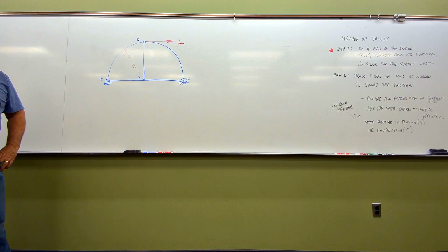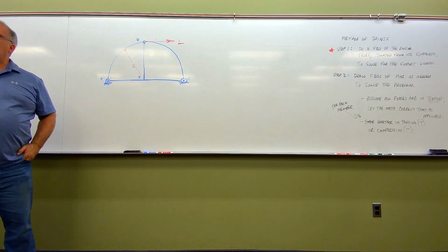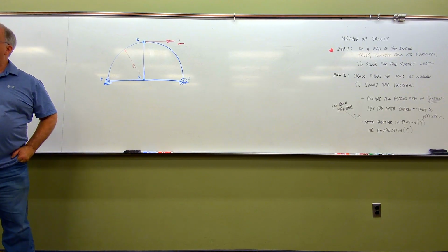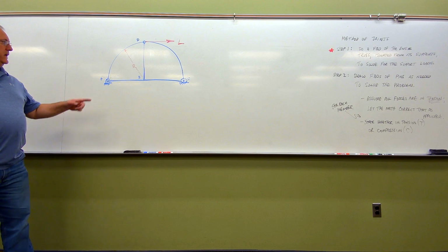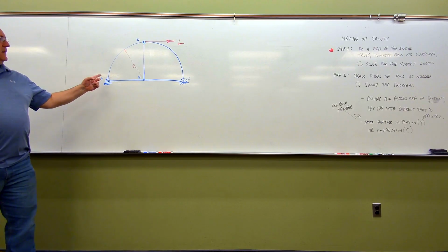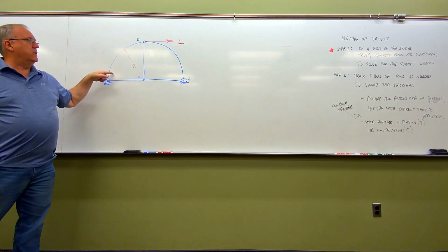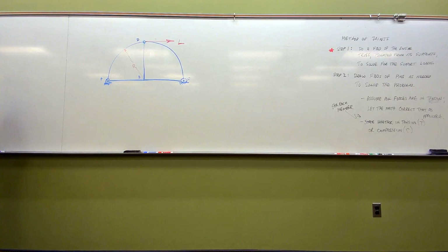So if you think about the line of action of forces in two-force members, the fact that this one here is curved, remember we've said many, many times, we don't care what the shape of the two-force member is. All we care about is it's got two pins and no weight, no applied forces. So that two-force member right there could easily just be straightened out and made into a triangular piece right there, couldn't it? So yeah, this is definitely a truss, all right.